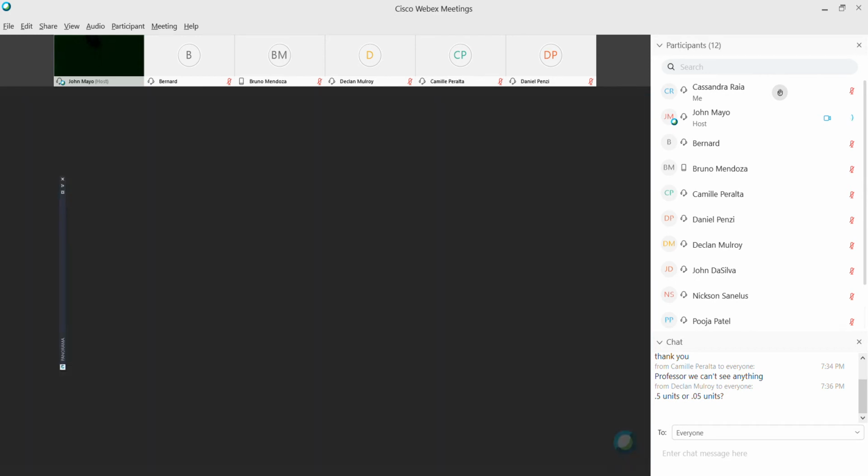So I hit OK as a break line. And now I define it as a boundary. I hit OK. And this time we don't get the illegal or self-intersecting polyline. So if I turn my layers back on, we can see now that our surface is limited to that boundary.